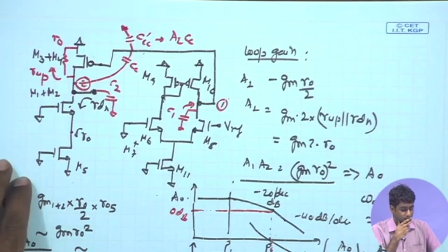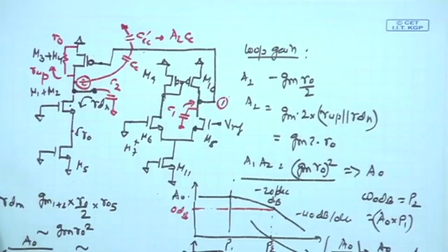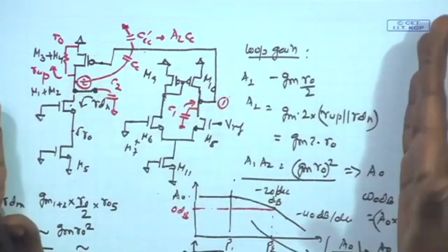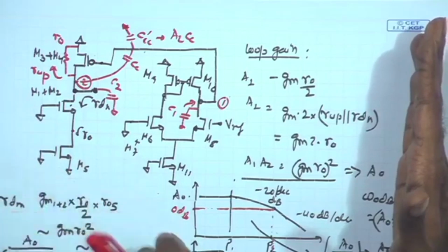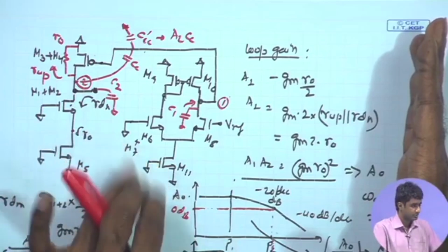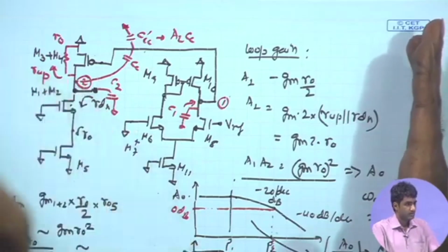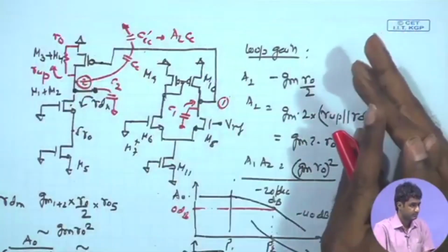For a one stage amplifier we can do this analysis, but if there are multiple stages, then how do we analyze phase margin and other things? Ultimately you have to make one of the poles dominant, at a much lower frequency as compared to the others. So, even if you have 3 stages, ultimately the target will be to choose one of the nodes which can be made the dominant pole. You can push it towards much lower frequency conveniently. That will become our dominant pole. And if there are other poles, but they are at sufficiently higher frequency than this one, then it is okay, you can still meet the phase margin.